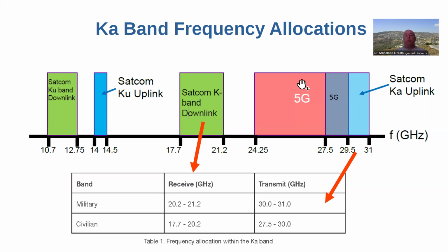What's interesting nowadays, of course, is the 5G band from 24 to 29 gigahertz, and everything I'm going to talk about really applies to these bands as well. We can utilize all the techniques I have for building a base station or a small cell site for the 5G market, even though a lot of the receivers and antennas there are planar and not parabolic like in the Ka band.